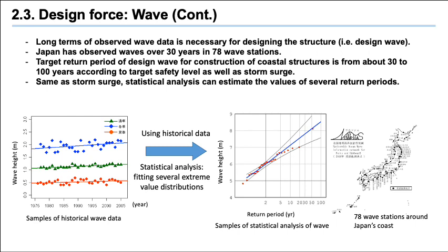Next, I would like to explain how to set the design force, wave force. The design wave is necessary for design of coastal protection structure. The long term of observed wave data is necessary for designing the structure. That is design wave. Japan has observed waves over 30 years in 78 wave stations.